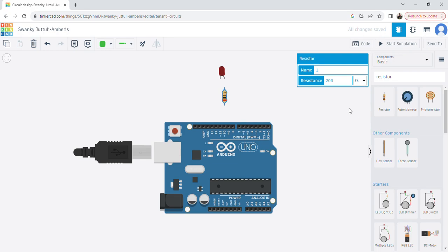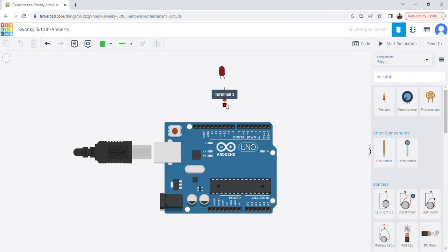Okay, so you can select the symbol, the symbols are given. From the symbols you can select the thing. Fine. Once you set the value, just click outside, that window will go automatically. Now what I want to do, I want to connect this particular component, obviously with the help of wire. Okay, so we are supposed to connect those, and for connecting, just go to the terminals.